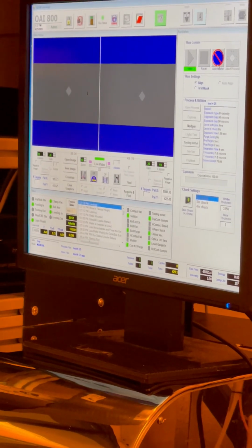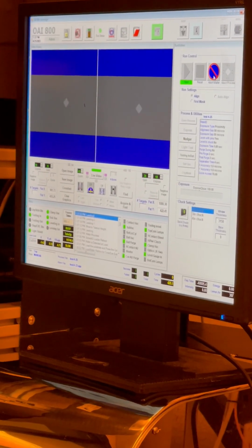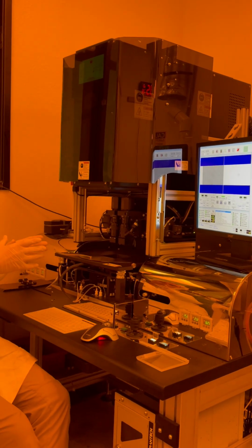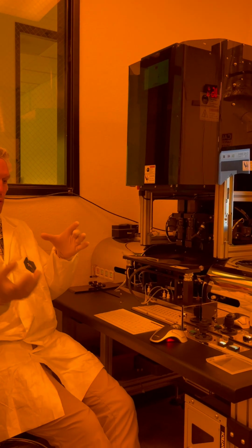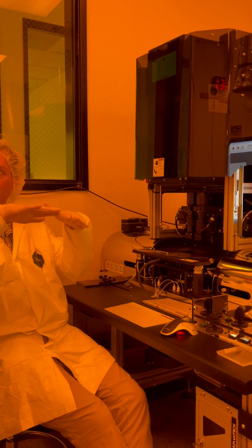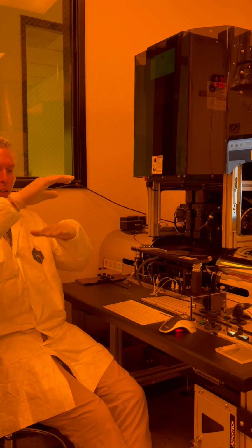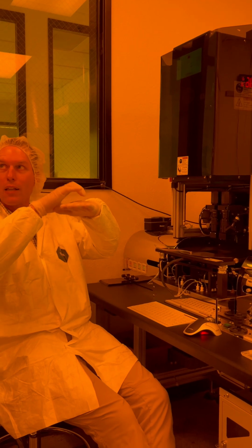Can you talk about the wedge edge compensation thing? Yeah, that's what it's doing right now. So it brings those three spacers in. And then what happens is, and I'll show you on the chuck, it basically flows nitrogen under the chuck, and the chuck surface can flow like this. So when it contacts those three spacers, the surface will planarize to the mask with the three spacers, and then lock itself in place.